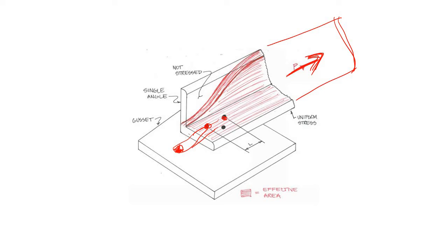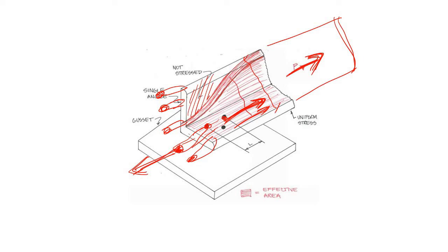Now definitely you can see that all the fingers are not being pulled simultaneously, right? Let's say these are the 5 fingers, only a single finger is being pulled. So naturally in this location there will be no such stress. Now as you go away from the load application point, the stress is applied over a wider part. Nearest to the load application point, this width is very small, but at the farthest point here, the whole cross section has been stressed uniformly.